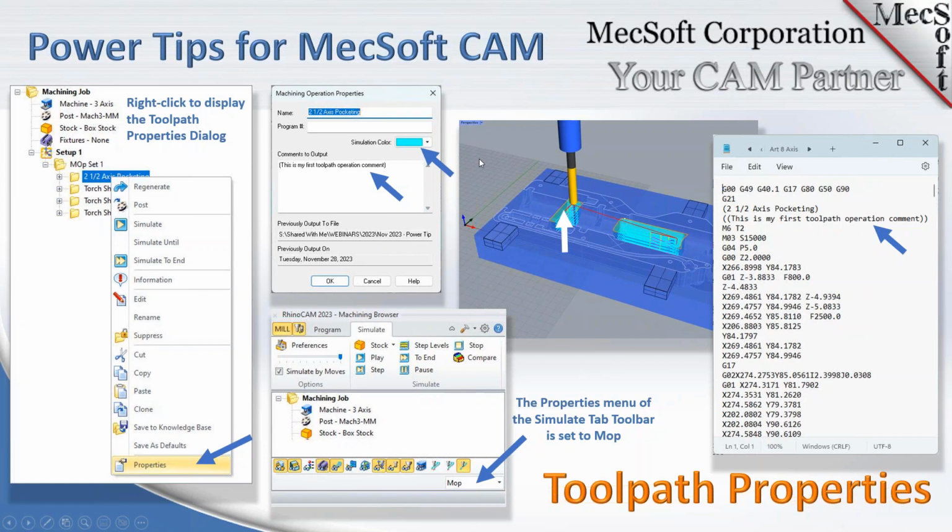One other note, Don, on the comments to output, it doesn't necessarily mean you just have to output comments. We've actually added G-code output there as well. Yeah, I believe if you wrap it with a % sign, it'll be output as G-code, not as a comment. So you can actually set up some specific G-code that you want output for a particular machining operation here if you want it. And also, it's got some properties information at the bottom. Previously output, your file name. That's good if you're running a lot of toolpaths and you're archiving your G-code. This will tell you what file name was used and when it was last posted. So that's some good information for you.